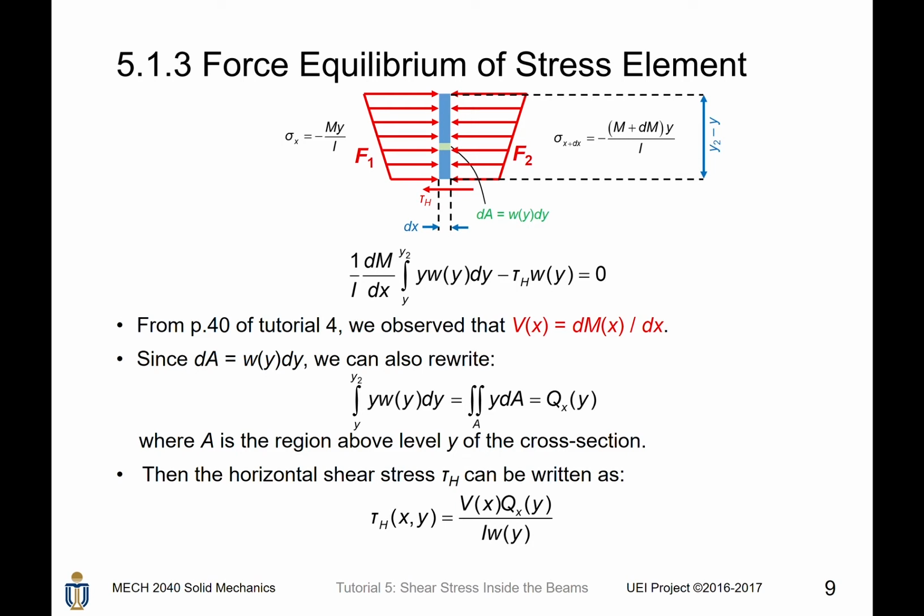If you have read our tutorial notes carefully in the last tutorial, we mentioned a very important relationship, which is that the shear force equals the differential of moment with respect to x. That is, V equals dM/dx. Therefore, this term simply becomes the shear force acting on this cross-section.